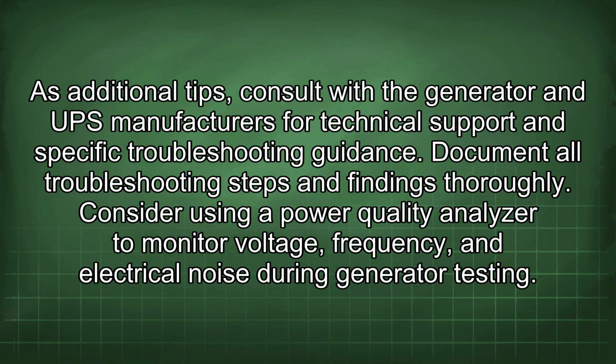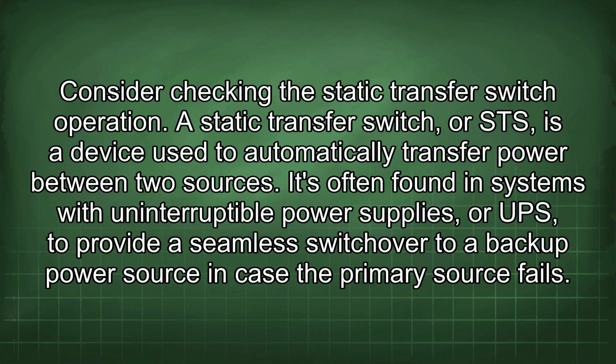As additional tips, consult with the generator and UPS manufacturers for technical support and specific troubleshooting guidance. Document all troubleshooting steps and findings thoroughly. Consider using a power quality analyzer to monitor voltage, frequency, and electrical noise during generator testing. Consider checking the static transfer switch operation.